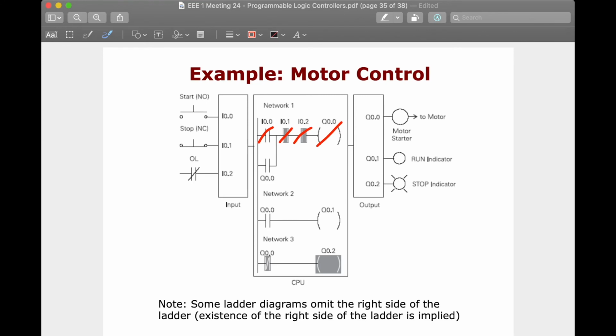So that means this is technically also shorted. So when we let go of the push button, it will just get depressed and become open again. So this one becomes open, but then energy from the coil is still going to be continuously energized because of this one here, because of the signal here.